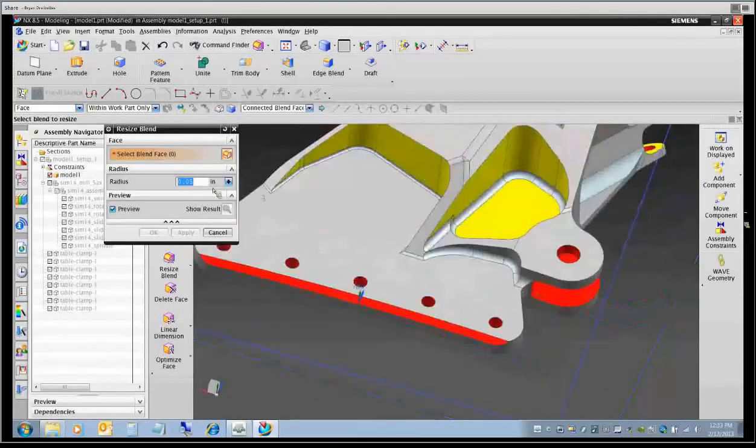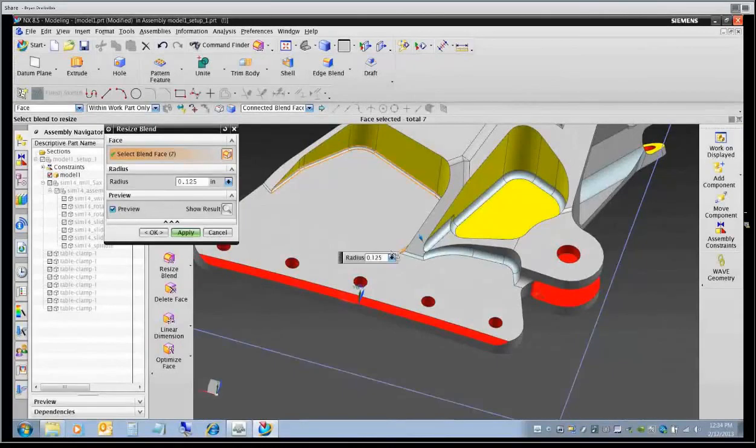And again, you could make these changes to any size. You may want to drive and see how large a blend radius would be. We can go ahead and make those kinds of changes with this also, right? So there, if we go back, we'll say resize this blend again. We can select that. It finds all those blend radiuses. Maybe we want to make this a 1/8 inch blend, right? You can go ahead and do that. So it'll show you the preview for that, right?